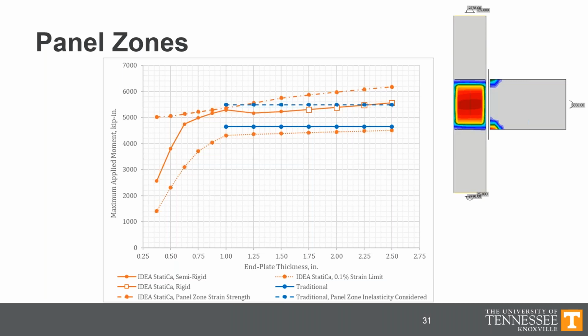Now, if you were concerned about this and really would prefer to have the smaller of the two strengths, one thing that you could do is change the plastic strain limit to something quite small. Here I changed it to 0.1%, which might be a little bit overkill. 1% might do. And what you see when we change the plastic strain limit, so as not to allow as much yielding to occur, is that the results are comparable to the lower strength in the AISC Specification Chapter J.